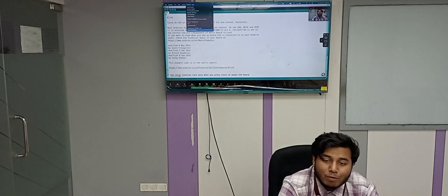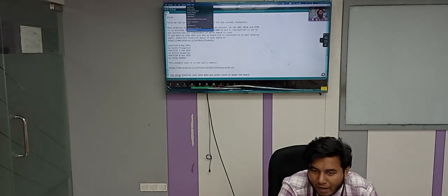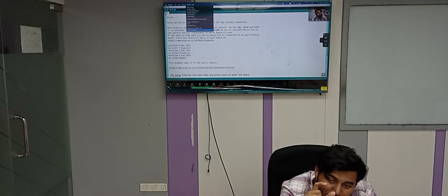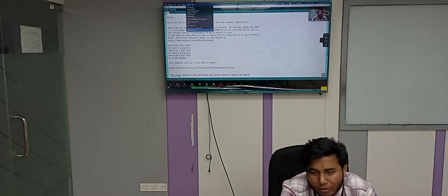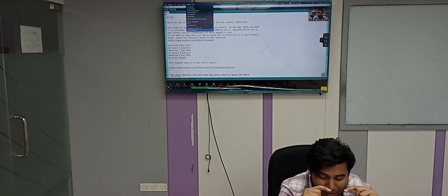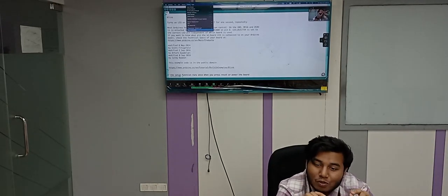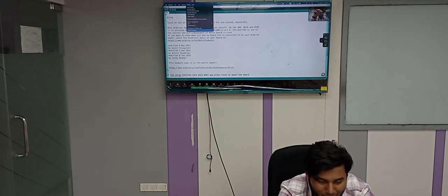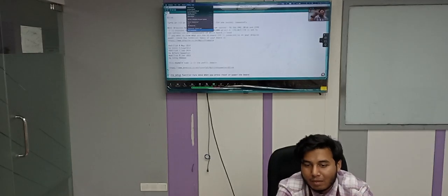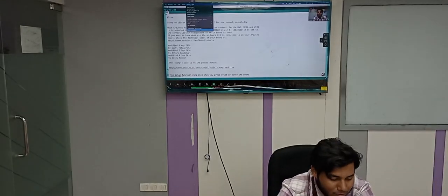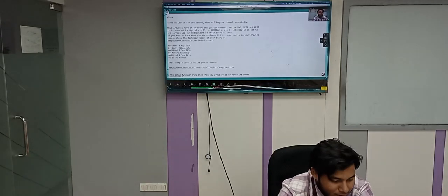Okay, so you have to build it on your own PCB or by hand, you have to solder it. Then you will upload the code to that particular ATmega328P with this bootloader, because on that particular Arduino board there is no port, no capacitor, no connection underneath the pins of the MCU, ATmega328P. Okay, so the Arduino board is very prominent.